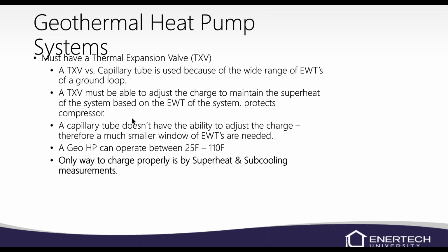Obviously, the expansion valve is there to adjust the charge to maintain superheat based on the entering water temperature, and it protects the compressor. Stops that liquid from getting back to the compressor. Compressors don't like to pump liquid. It doesn't compress. Obviously, the cap tube doesn't have the ability to adjust the charge. Again, we're operating anywhere from 25 to 110 degrees, depending on the season.